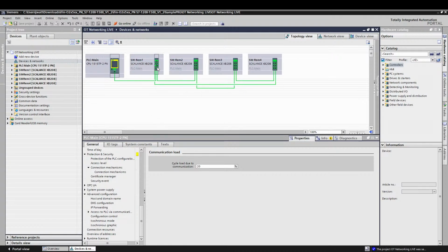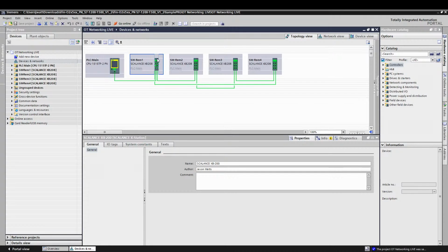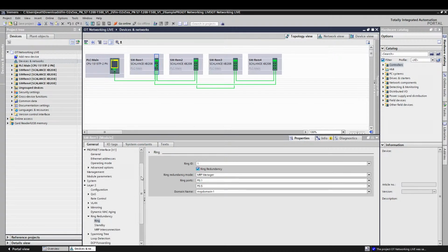Say this switch gets hit by lightning, you plug in a default switch of the same type with this exact same configuration. The PLC sees it, downloads the program to it, updates all of the parameters, and then you're up and running. That's called device replacement without download or something like that. And I thought it was on this, but maybe it's not. But absolutely, that is part of what comes with using the topology. But it can be annoying.